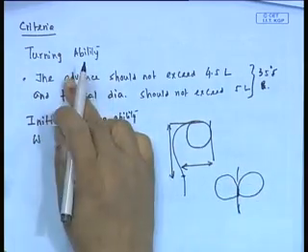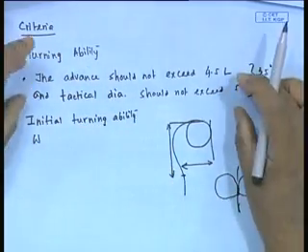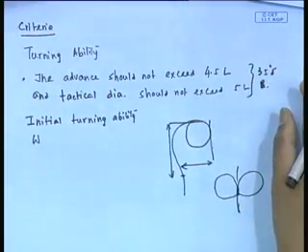The test says it has to be done at 35-degree rudder or at the maximum rudder permissible as you design. Most ships are designed with 35-degree rudder, but for both port and starboard sides. My question is, why both port and starboard sides? Give me a reason why. What could be a possible cause why port turn and starboard turn may be asymmetric? Slightly, even if slightly.